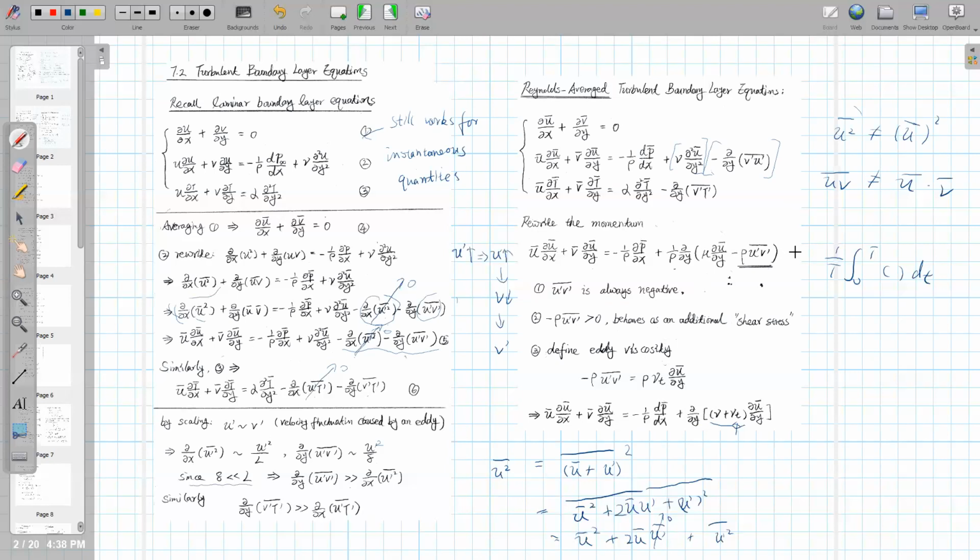At that point all the kinetic energy is dissipated into thermal energy. So we have a one-way direction from large eddies to small eddies. The reason this term is always negative is that this negative direction represents transfer from the large eddies to smaller eddies.